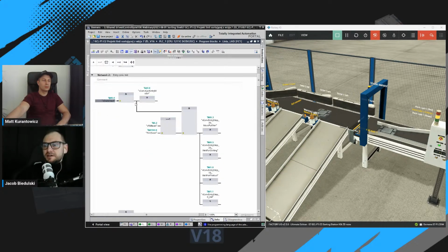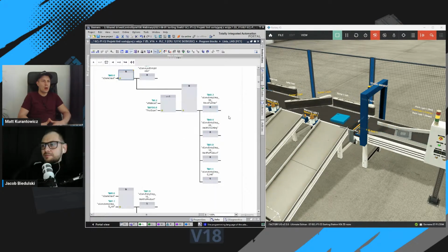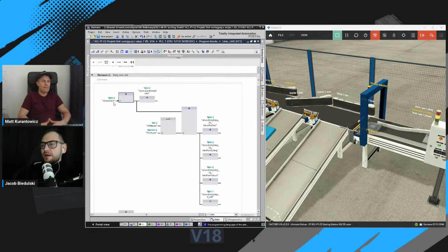Right now, you can see the FBD structure. It is a little bit different. In ladder logic, we created logical operations by structuring normally open contacts and normally closed contacts, like in an electrical diagram. Here, the structure of the ladder logic was converted to logical gates. We have instructions like AND, OR, assignment instructions, set, reset, and so on. And those operations are converted into functional blocks right here, okay?